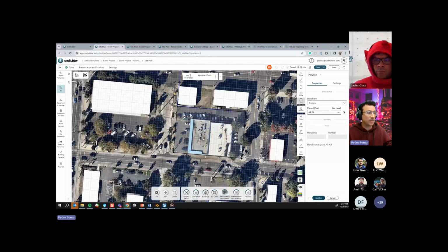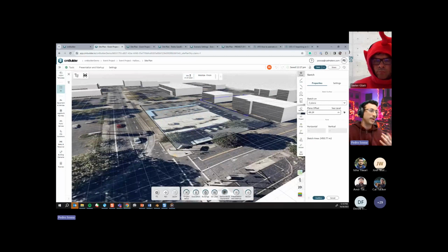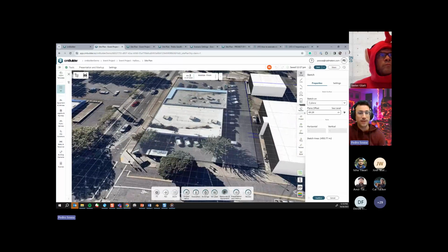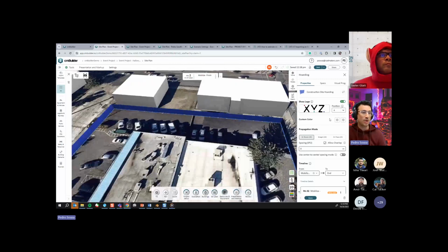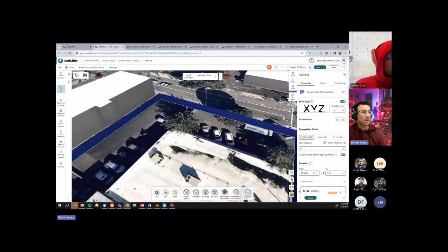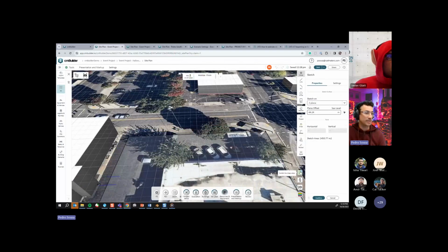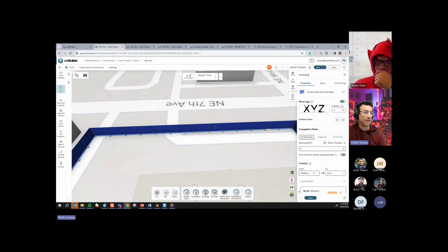The reason why I want to talk about the fence is that sometimes people do not notice that you don't need to place a point for every single segment. You can use fewer points for a fence, which makes the fence work better, because the fence has a mechanism where you have the allow overlap. How the allow overlap works is that we take each line of your sketch, and we start the pattern of the object from one point and also from the other point, and we overlap them in the middle. So you have a nice and clean overlap like this.